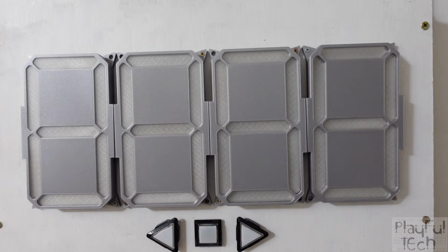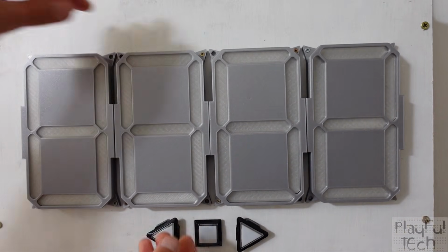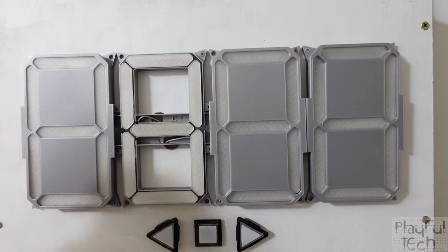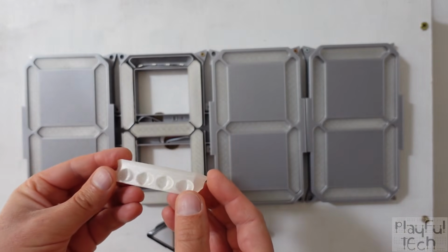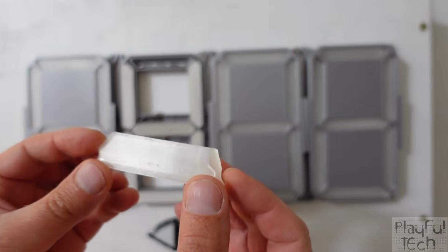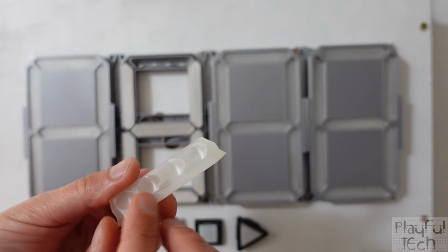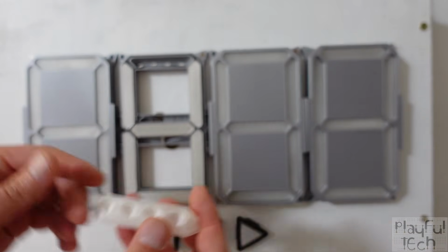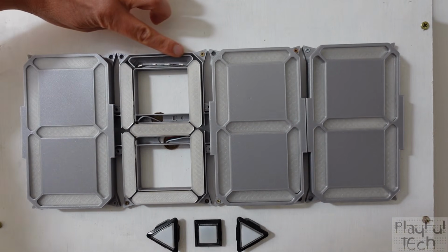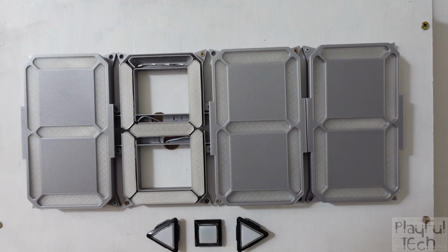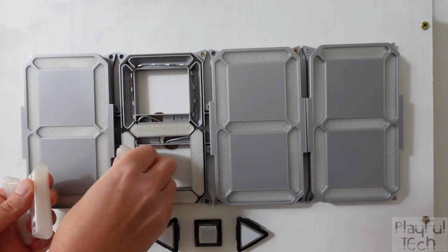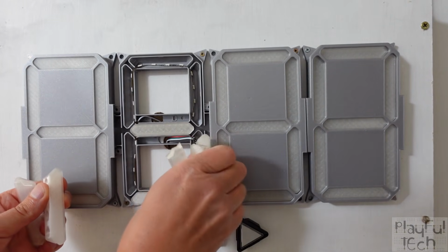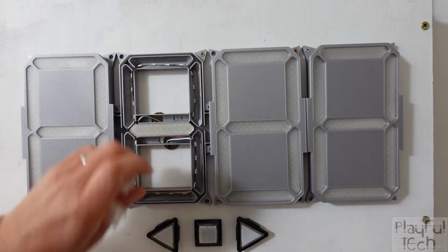So now let me demonstrate the display I was using at the start of this video in a bit more detail. So this is 3D printed, and if I pull the cover off one of the digits, you can see the components underneath. Each segment has one of these covers on it, which is printed in transparent PLA. And you can see it has 4 recesses on the side here, which line up with the 4 LEDs in the strip in this segment. And these covers hold the LED strip in place, and they also act as a diffuser to spread and soften the light in each segment.